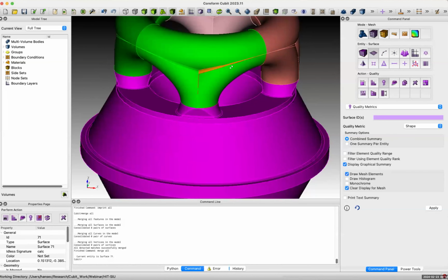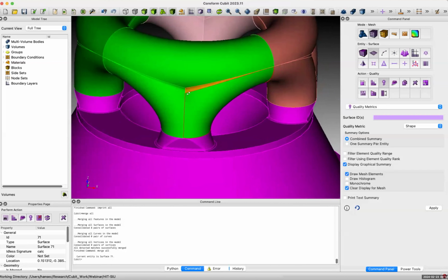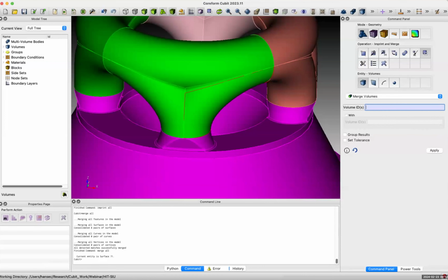The way I'm going to resolve this is by compositing those surfaces onto the adjacent surface. And what this allows is for elements to go across this region. Normally, all your curves are going to be meshed first, and triangles can't go from one surface to another surface. But compositing creates a virtual surface across the whole region, which allows triangles to go across. You're going to miss some of the geometric fidelity there, depending on your resolution, but you're also going to get rid of this really sharp region.